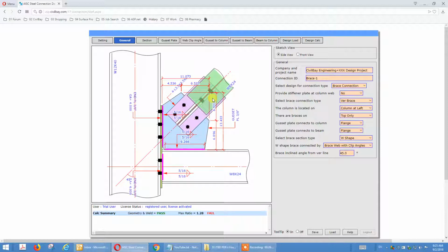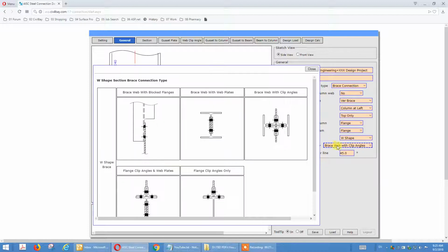We want to utilize the largest radius of gyration of the plane. And the other case is the horizontal brace case. We want the wide flange brace, horizontal brace, to be vertical, okay? To avoid the accumulation of dust, rain on the web. Okay, so that's the themes.